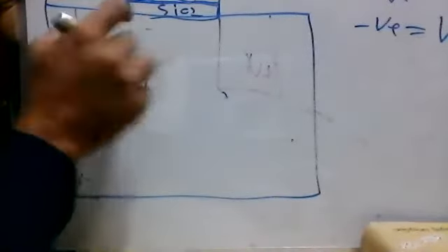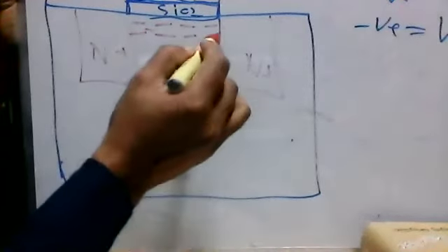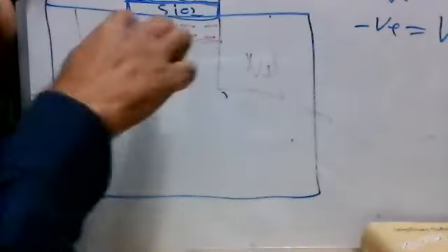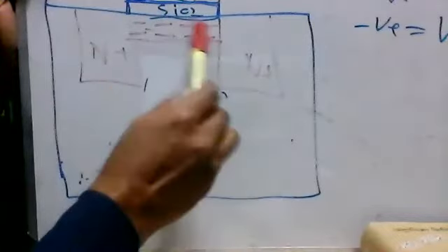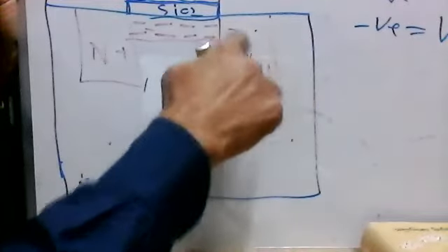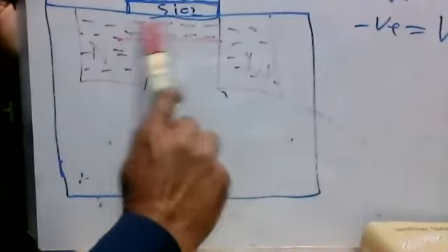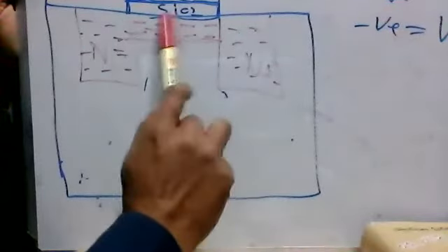What will happen? All the electrons in here will be aligned here. So this will be a channel. Right? Now you see here all the electrons are here, and we know that this N plus means full of electrons, everywhere electrons, right? Full of electrons. So now all over the place is electrons, and in here this is called a channel. We call this one a channel.